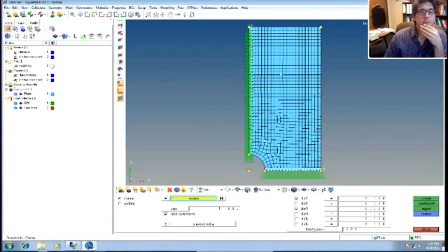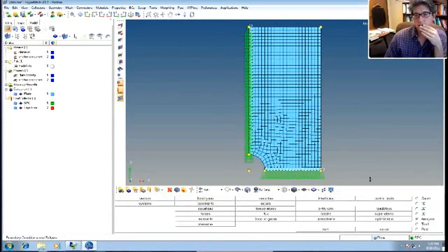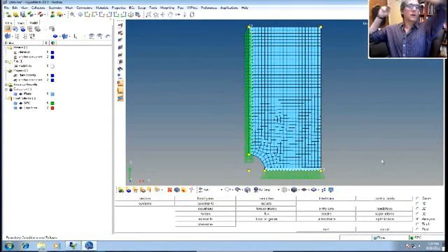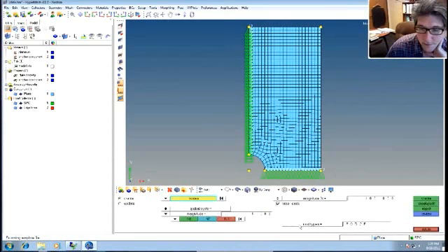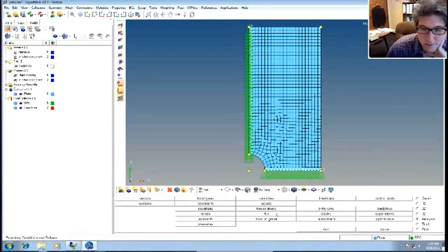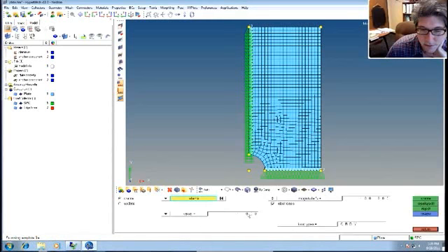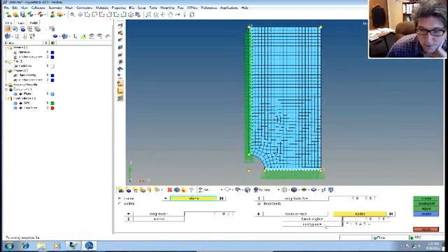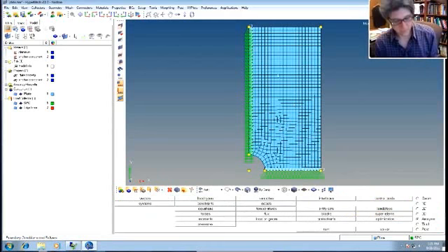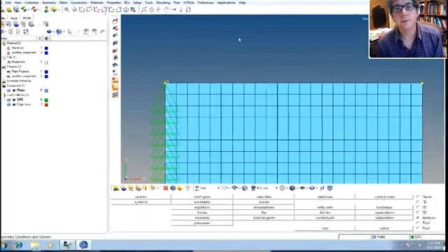Now the next thing we need to do is put the force on top. You can actually do P-load 1 cards in here, I think. Let me just check. Do they have those? No. Okay. Let's see. I'm just seeing which ones let me do a P-load card. So you can do the P-load options here, but they're a little tricky. We haven't talked about them too much. I'm actually just going to put the forces up here manually, by hand.